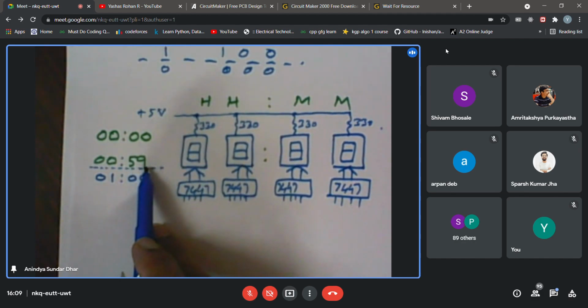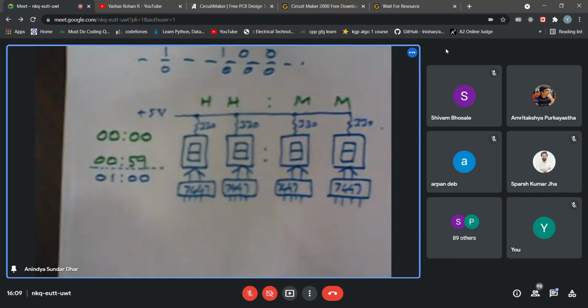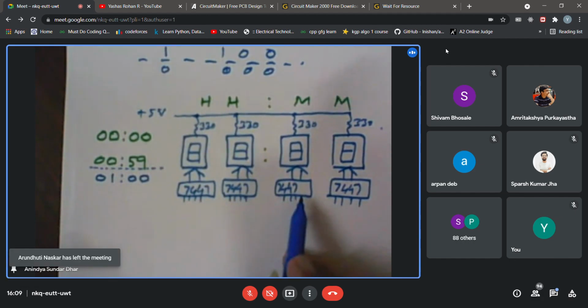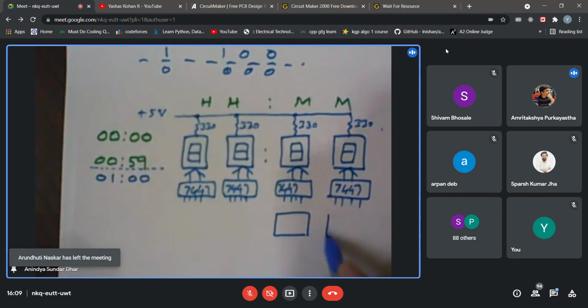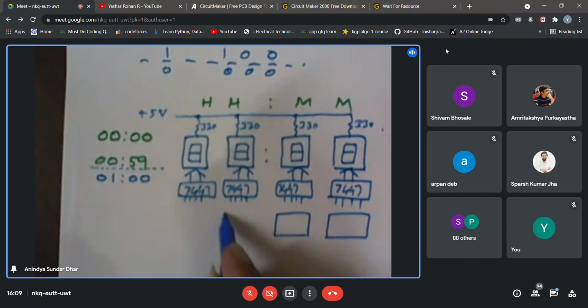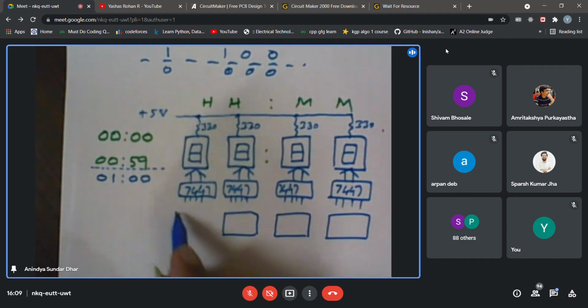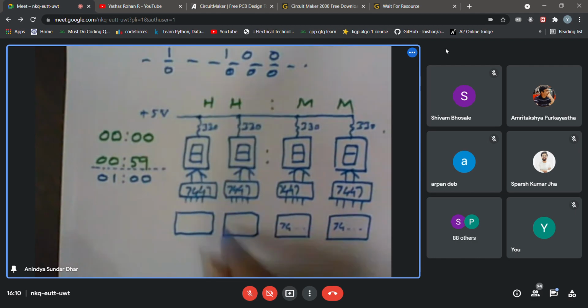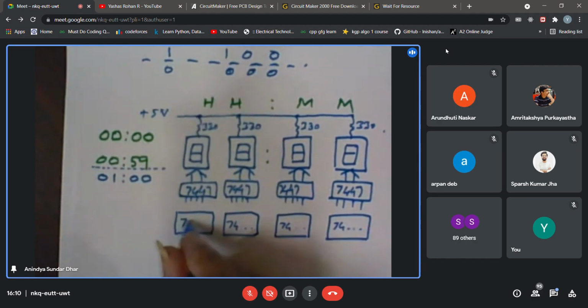The first clock anyway, I am assuming I can design a clock signal with a 1 minute time period, and that will trigger this first digit. Who will tackle the second digit? So I must have some sort of counter in each of them. You may use 7490, 7493, or a combination of them as you may need. The only restriction is that they should be 74 series ICs right now. Later on, we can remove that restriction also if you wish.